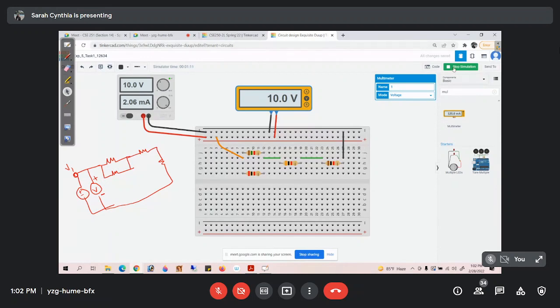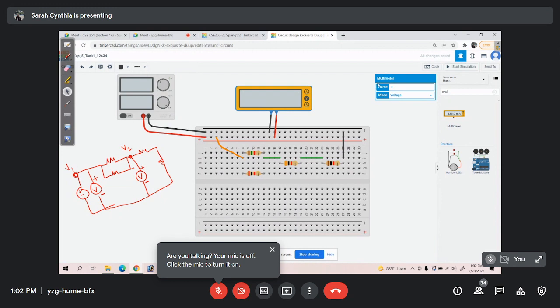Okay, so did we all do this? Did we all check the voltage? Okay, so what's the next thing that we had to do? We had to check the voltage of this particular node, that is V2, right? In order to find the voltage of this node, we will have to place a voltmeter over here that has a positive terminal here and a negative terminal here. So let us use this same voltmeter. We don't have to take another voltmeter.